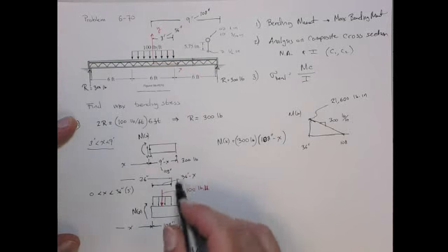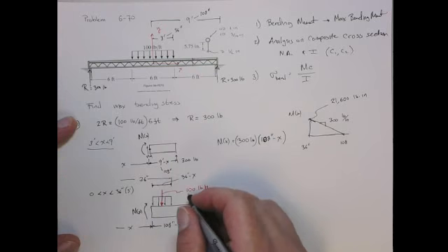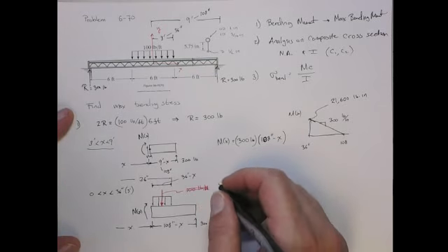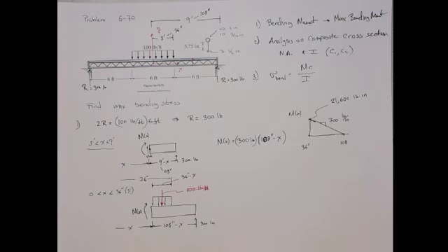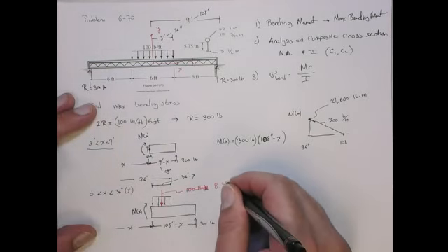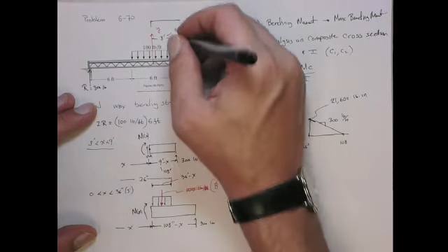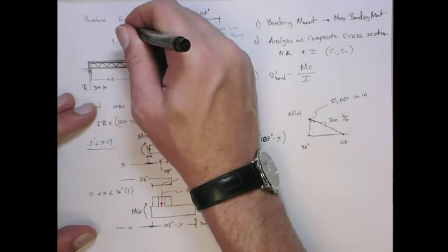It's distributed over this 36 times x, but I have the feet down here in the units, so I should probably not use the 100 pound-feet, but really 100 divided by 12 to get it in pound-inches, right? So now that's 8.33 pounds per inch, right? That's this distributed load. This is divided by 12, 8.33 pounds per inch.